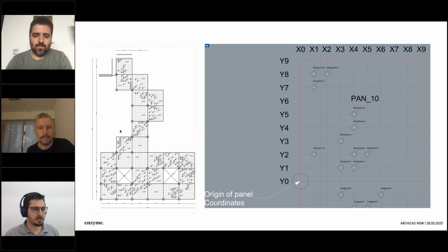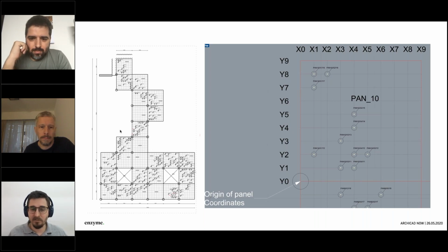The process was similar to the other feature that I showed you. We sent that piece of the model from Rhino, created the feature using Grasshopper and Rhino, and then sent the 3D model separately using the live connection, with all the information we wanted embedded in the elements. To avoid manual placement of IDs and labels, we created all these diagrams in Rhino in 2D and sent them and linked them to the ARCHICAD worksheets or ARCHICAD details, etc.